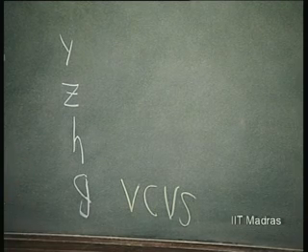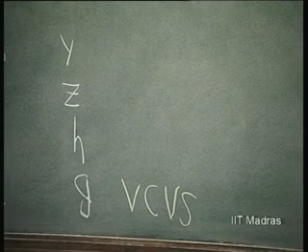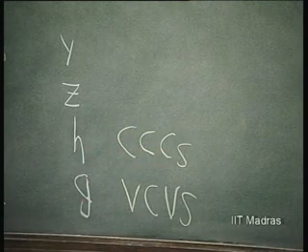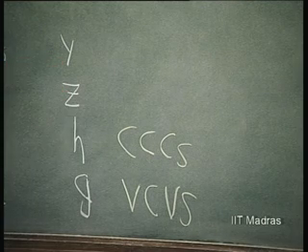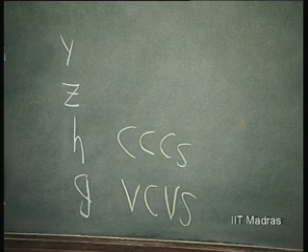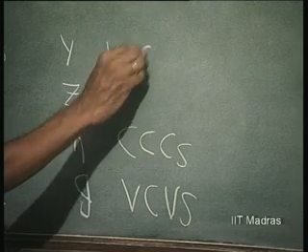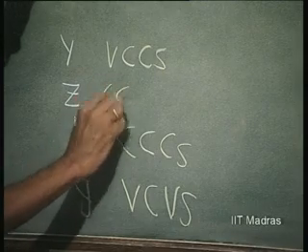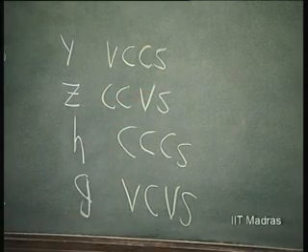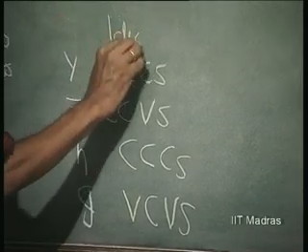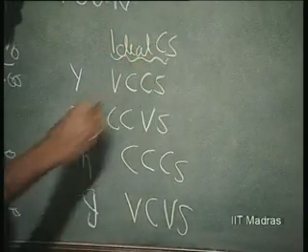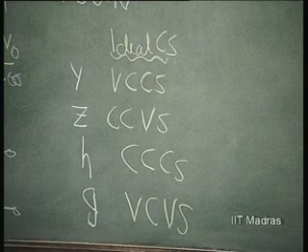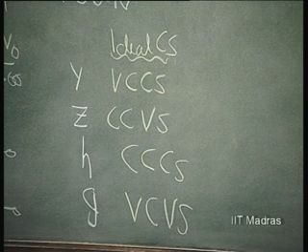The H parameter will ideally define a current controlled current source, and the Y parameter will define a voltage controlled current source. The Z parameter will define an ideal current controlled voltage source. So, these ideal control sources can be defined only by these parameters respectively. This we had understood in the beginning of the course.